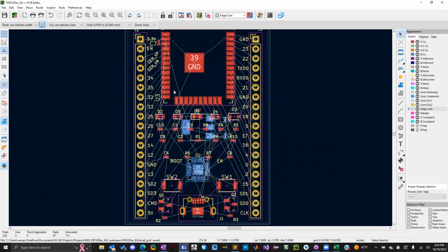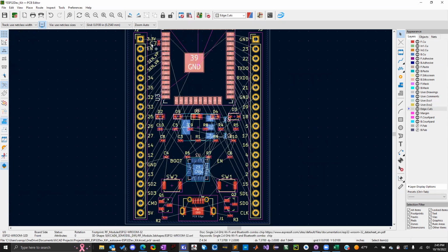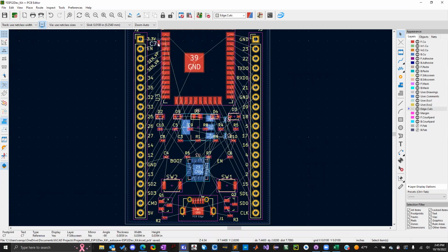And then just start organizing components. Pay attention to the lettering here. So D2, D5, D1. Make sure it's exact. Everything red is on the front copper. Everything blue is on the complete back side of the board. And then the only thing that's going to be in the inner 2 layers are going to be through hole connections.